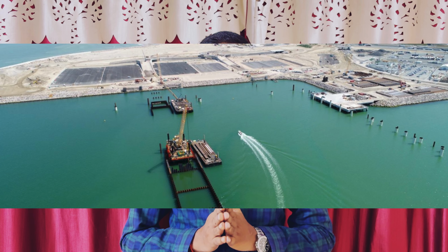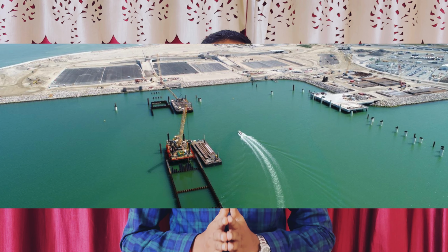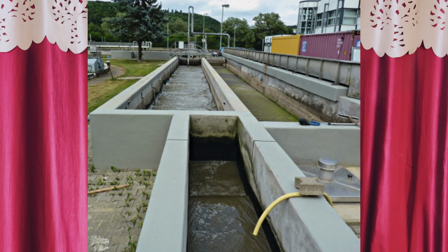Is your concrete structure in direct contact with seawater or chemicals? Then your exposure condition is very severe. The last question, is your concrete structure going to be fully submerged in seawater or under chemical attack? Then your exposure condition is extreme. Always consider the worst possible exposure, not the present condition.